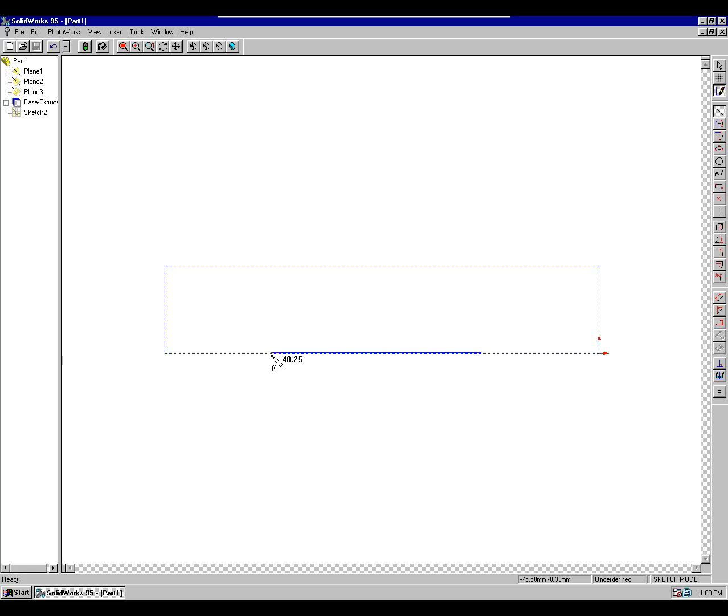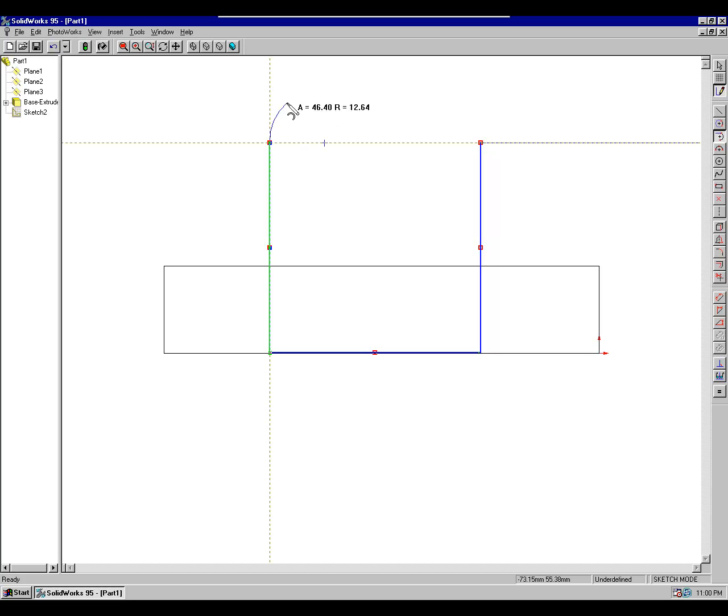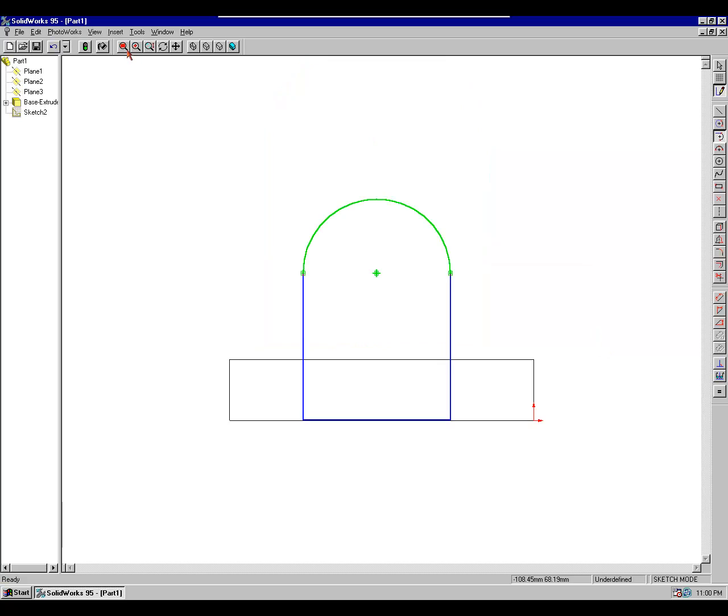So you can see I'm actually not able to pick up model edges at that point in time, so I'm going to have to go back and actually add that dimension manually. So you can see there I'm going back. I didn't have the gesture into an arc, but I did have tangent arc, so that made my life a little bit easier. And I still had zoom to fit. You can see I put my dimensions in the same way I would in the Essentials class right there. I'm putting in the height, we'll put in the radius of that arc, and we'll put the distance from the